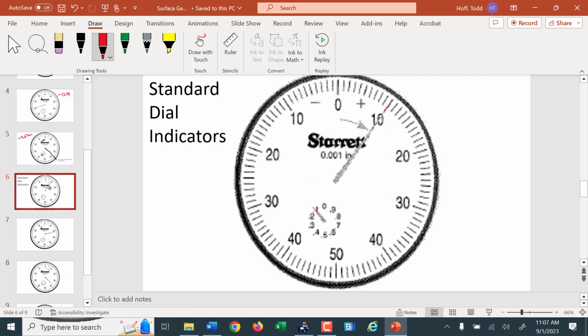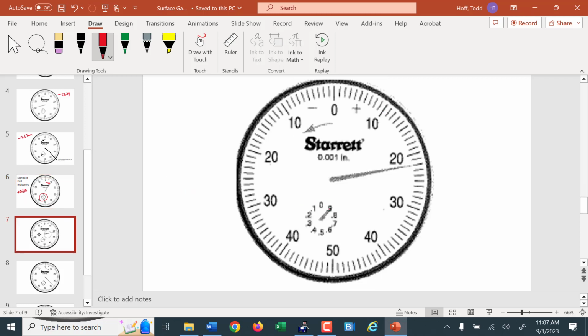So for the inch indicator, it's the same, just the decimal points moved over. Positive or negative? Positive. Now this is not whole inches anymore, it's tenths of an inch. So that is 0.1 and then 10. You got it. So this one, positive or negative? Negative.